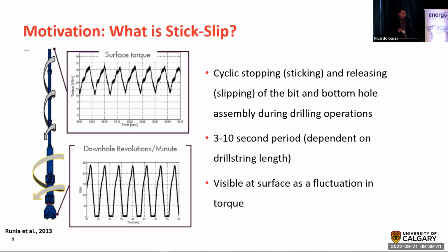First, let's start with a dynamic problem that's very well understood, which is something called stick slip. You rotate at one end, the bottom end doesn't have enough power, it stops every once in a while, sticks, and your drill string spins up or twists upward and stores energy. Once you have enough energy, the drill bit releases, drills for a little bit, runs out of energy, stops. So it's this very cyclic cycle, and it's very frequently seen. There are systems out there now that control for it.